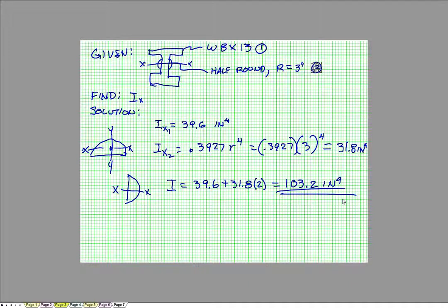Well, adding just a couple of little 3-inch half rounds in there tripled the strength on that, didn't it? Well, tripled the resistance to bending. How's that? So that's what those numerical values represent, the resistance to bend. Yes. Bend, buckle, twist, yes.